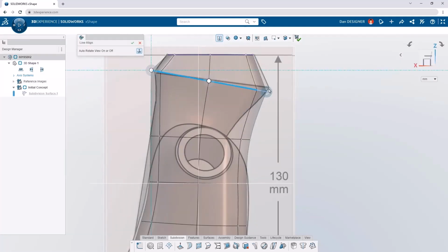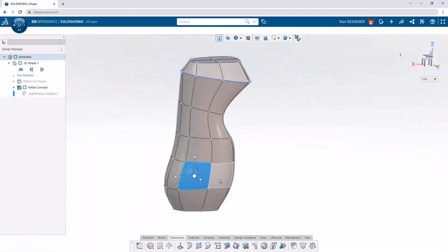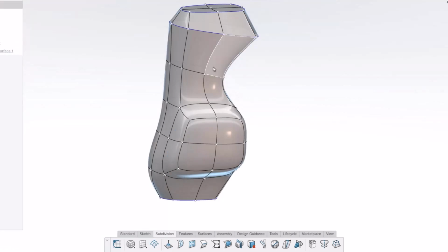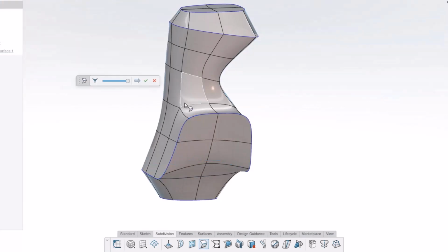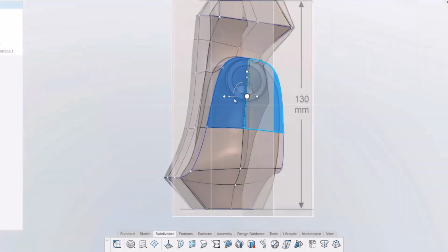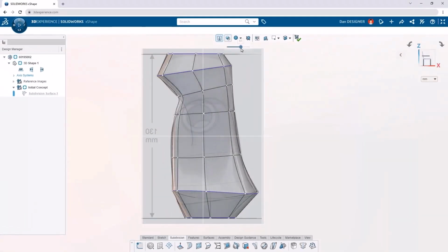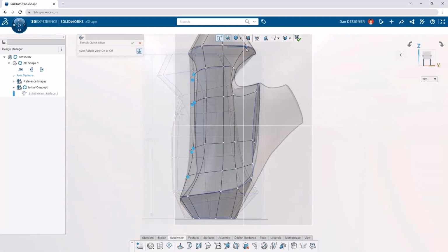You can drag and snap lines into place using existing geometry. From there, you can subdivide and extrude faces or insert entirely new edges or loops. Add features to your surface for style or function, and even align your surface to a curve you can draw on screen with your cursor or finger.